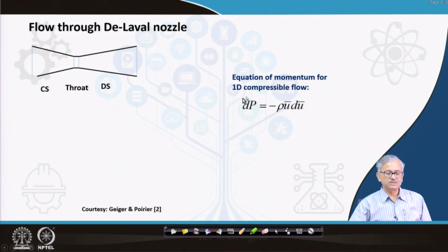Basically, you have the Bernoulli's equation. In this case, only the pressure head will be there and the kinetic head. There is no gravity head because it is horizontal. So you can consider that is the pressure; anyway, the gravity will not be very important here because it is a gas, it does not make a difference with the height.